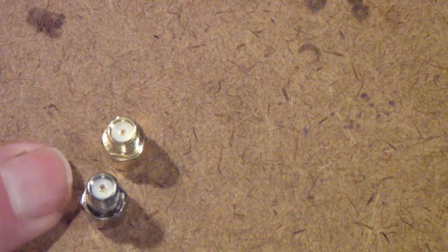But this would be a reverse polarity SMA, and you may find reverse polarity SMAs on a lot of routers and other Wi-Fi equipment. The reason for that is because the FCC was concerned in the early days of Wi-Fi that people would attach antennas with more gain than the FCC wanted to see, and so they required Wi-Fi manufacturers to use a connector that the FCC considered was not readily available.